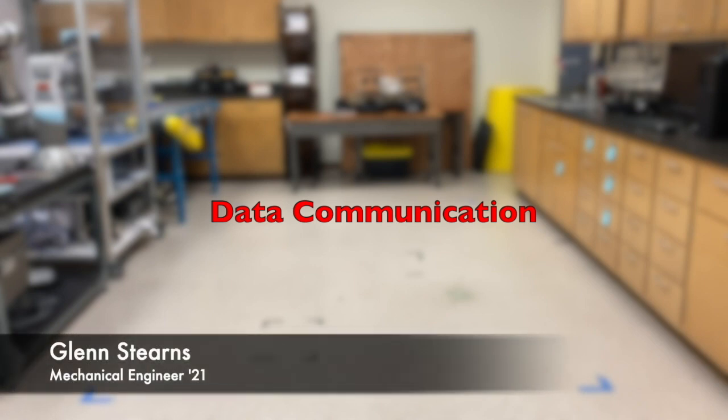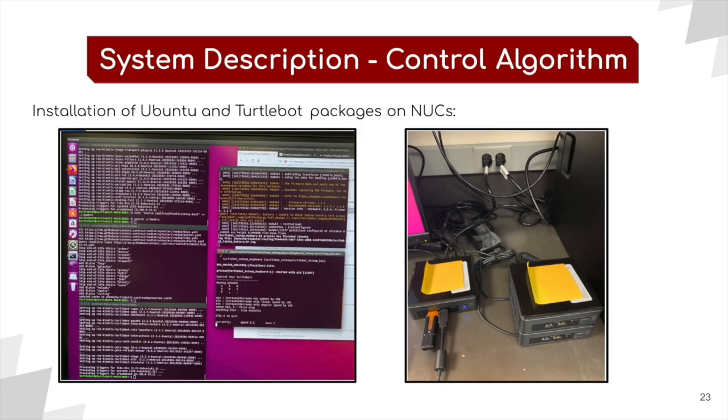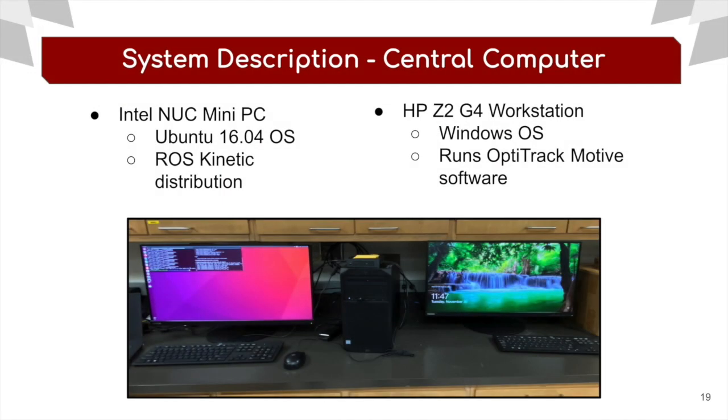To be able to control the Turtlebots, the Intel NUC Mini computers were all installed with the Ubuntu 16.04 Linux operating system. This is the latest version of Ubuntu that is compatible with the Kinetic ROS distribution package, which we are using for our project. ROS is short for Robot Operating System, and it is an open source robotics middleware suite, which provides a set of software libraries and tools that allow for hardware abstraction in its applications. We then installed the Turtlebot specific ROS packages along with other communication ones for the specific needs of our project.